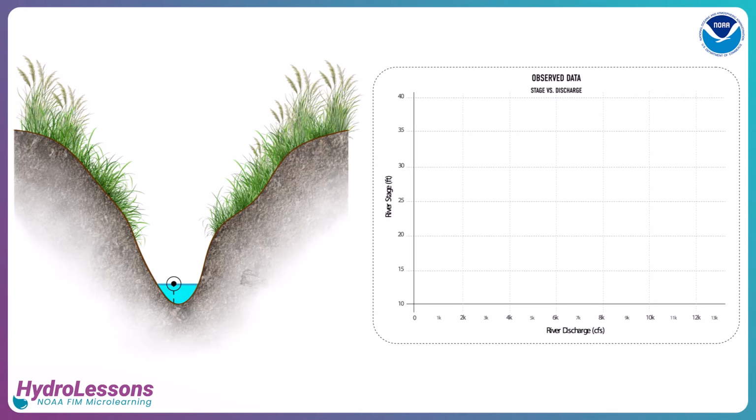Conventional rating curves are empirical, meaning that they are developed from repeated field measurements collected at stream gauges. Over time, hydrologists record stage and discharge across various flow conditions, plot the stage-discharge pairings, and fit a curve through the data. This curve can then be used to estimate discharge from an observed stage or stage from a known discharge. Due to the shifting nature of river channels over time, these curves require recalibration via regular field updates to remain accurate.